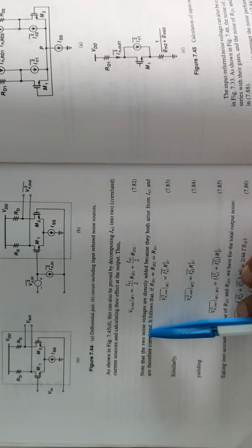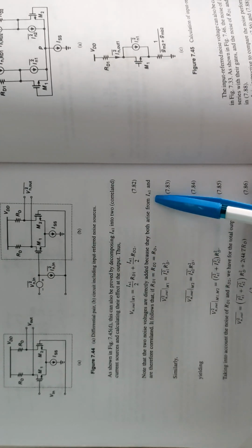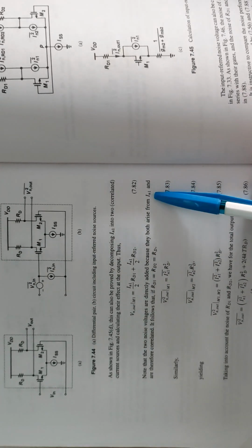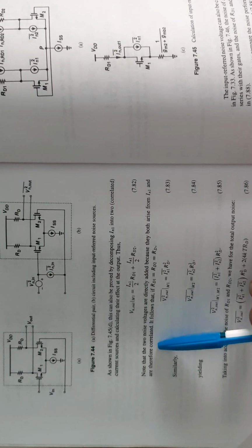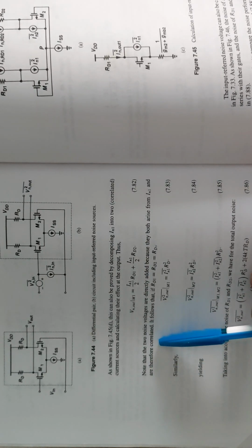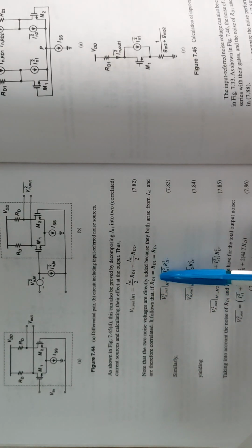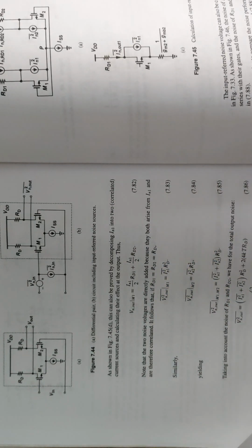Note that the two noise voltages are directly added because they both arise from I_N1 and are therefore correlated. It follows that if R_D1 equals R_D2 equals R_D,